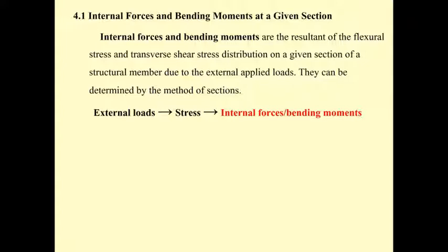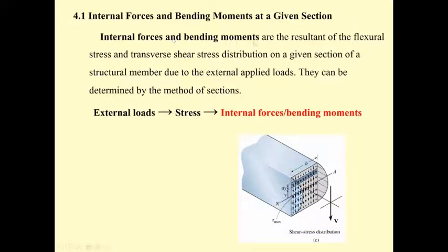By the definition, the internal forces and the bending moment are the resultant of the normal stress and transverse shear stress distribution on a given section of a structural member due to the external applied load. Like I said, they can be determined by the method of section.